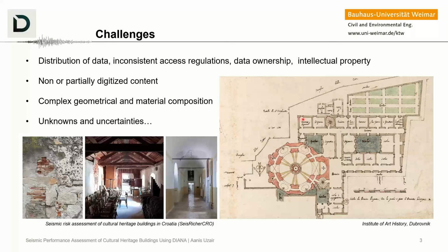This brings geometrical difficulties in your structural models or makes the mesh of the structure more complex when you model such peculiarities in the structural system. And this brings us to the point where we have to consider how detailed the structural model should be, what peculiarities you do want to consider in the structural model, and what information can be excluded from the structural system.